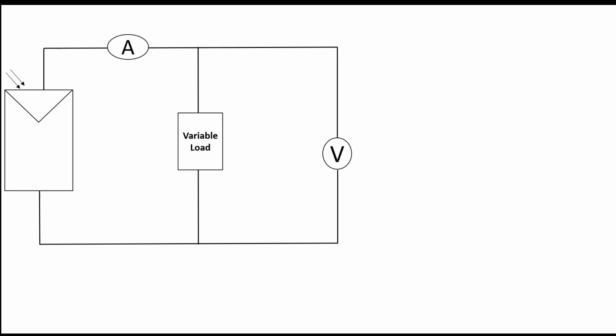To calculate JSC, short circuit current, or open circuit voltage VOC, or to characterize the IV characteristic of a solar cell or of a panel, you see a panel is connected across a load, and in that an ammeter is being connected so as to measure the current, and a voltmeter is connected across the load. So this way,